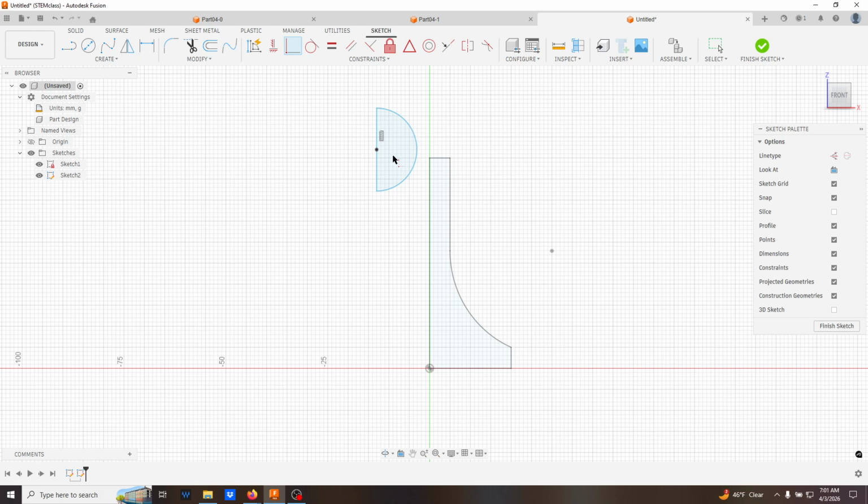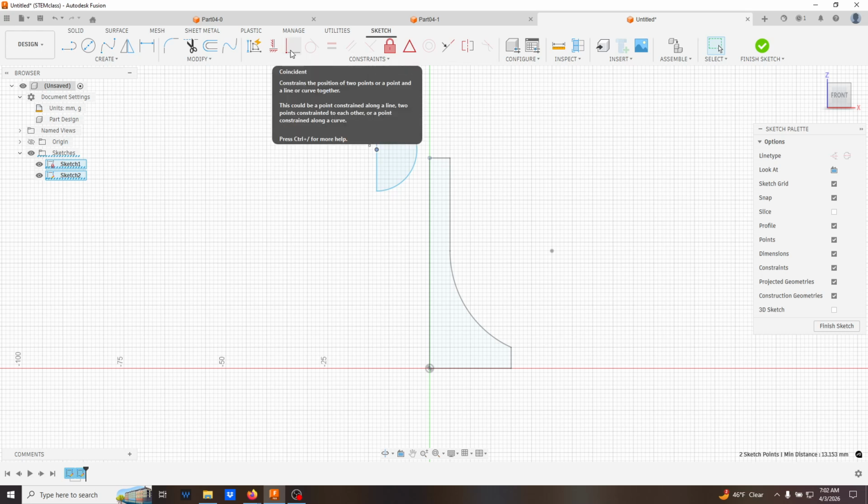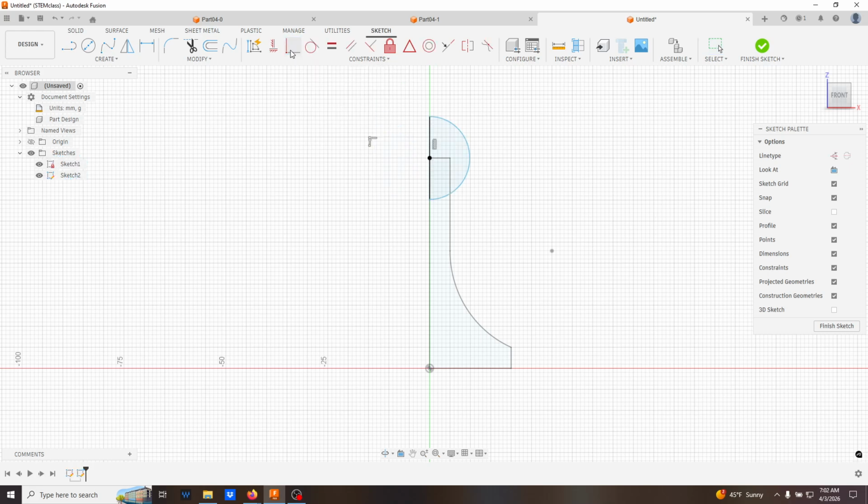So that concept is something that I like to bring up when it comes to assigning constraints, because you can do stuff different ways. But when it comes to how you assign constraints on sketches, and how all of these stack up together, some of those relationships can either be very helpful or bite you in the bottom. But just different ways, going back to the ideas, different ways to go at things. I think in a previous video I mentioned how I could set the centers of circles as coincident, or I can make the circles themselves concentric. So we get to the same place, but there is a difference in how we do this.